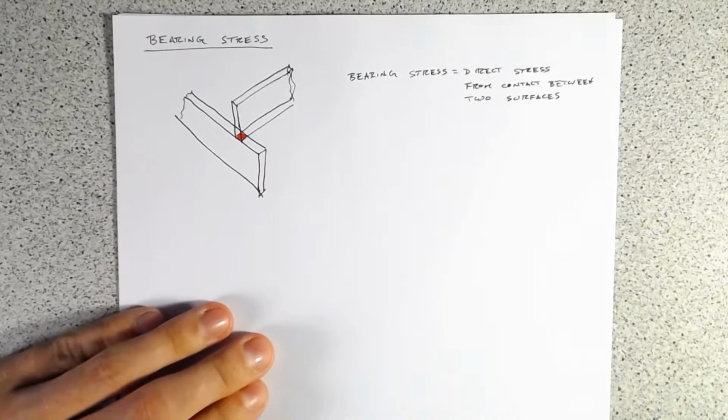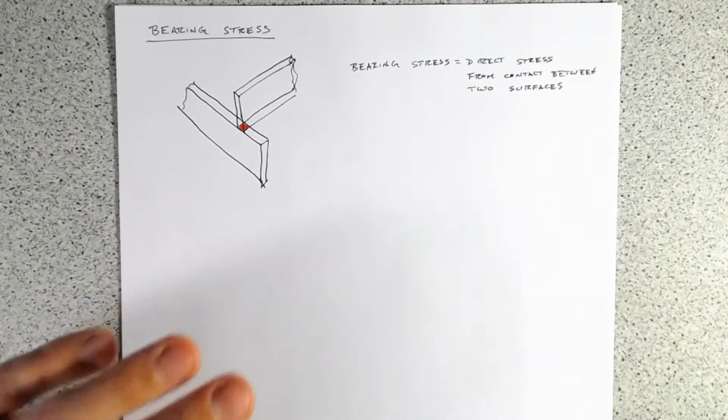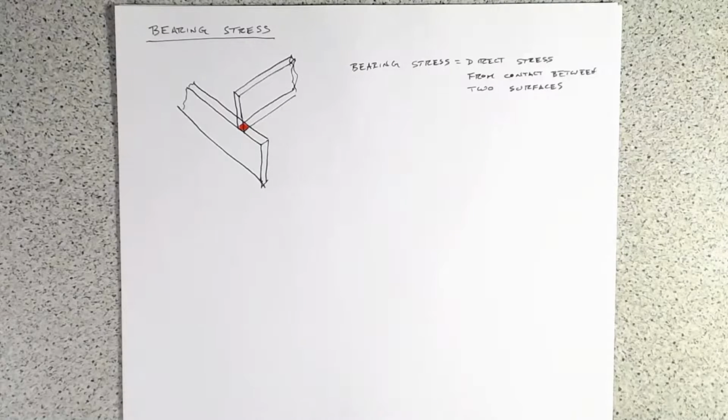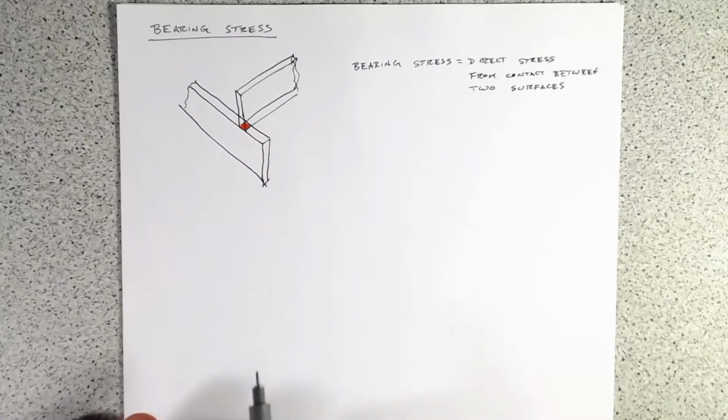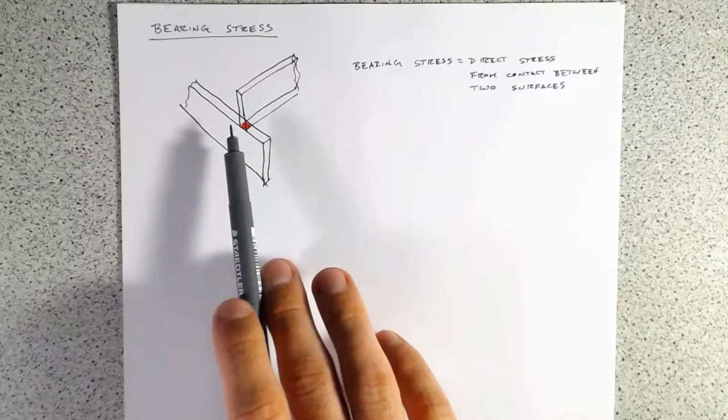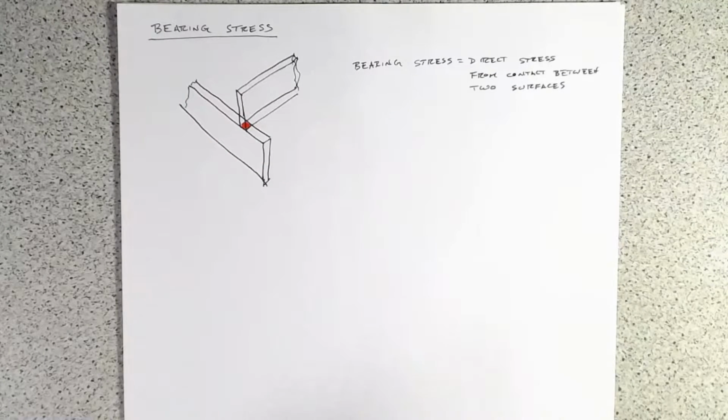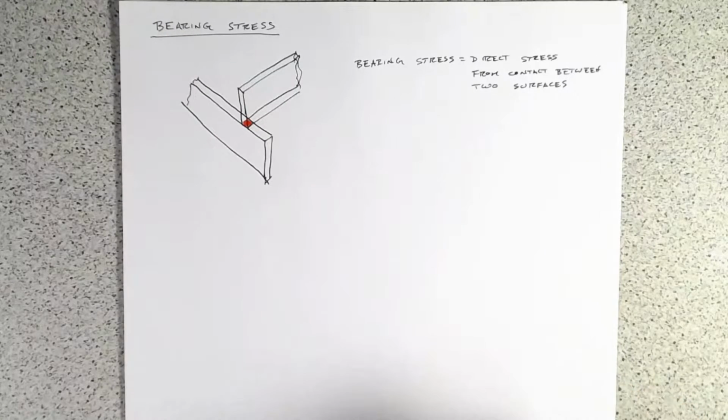But it often rarely governs in structural engineering. If you get into soils, that's bearing stress is a big consideration, particularly for shallow foundations. But again, it's an indeterminate problem. You need to understand the deformation of the material in this small section, that requires a lot of analysis, and it's often not worth our time. And we can still design a safe structure without it.